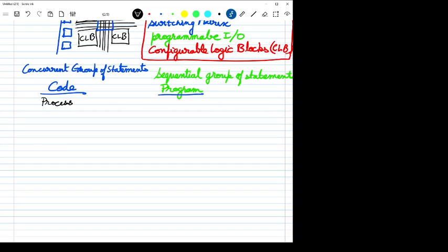Now there were lots of things which were different. For example, Verilog used to have something called standard delay format, which later was adopted in VHDL also to specify the signal delays. Then it became easy for VHDL to use a Verilog block, so these two languages could mix together. Still, most test benches are written in Verilog, because they are more or less sequential. Test benches in Verilog.